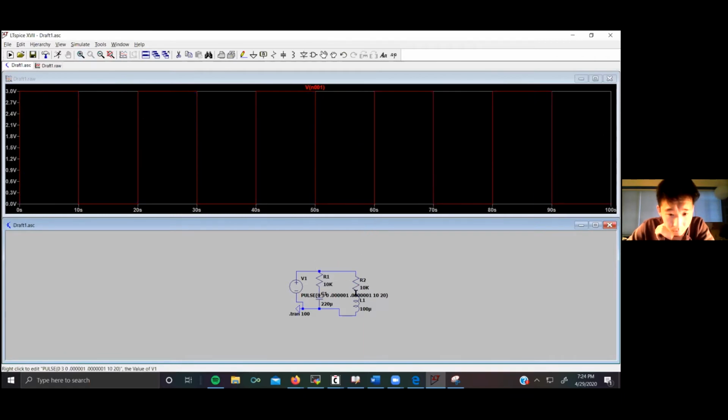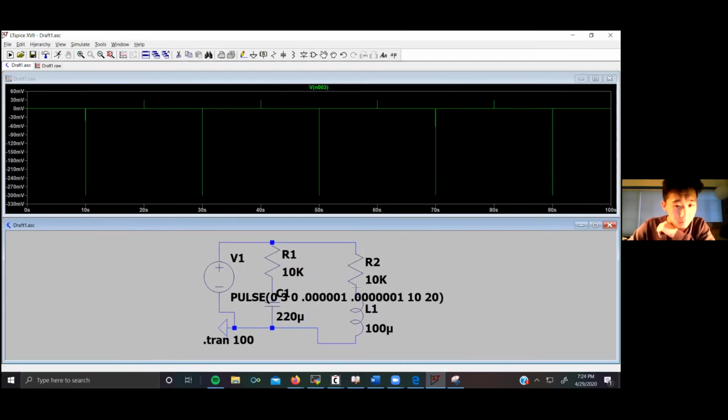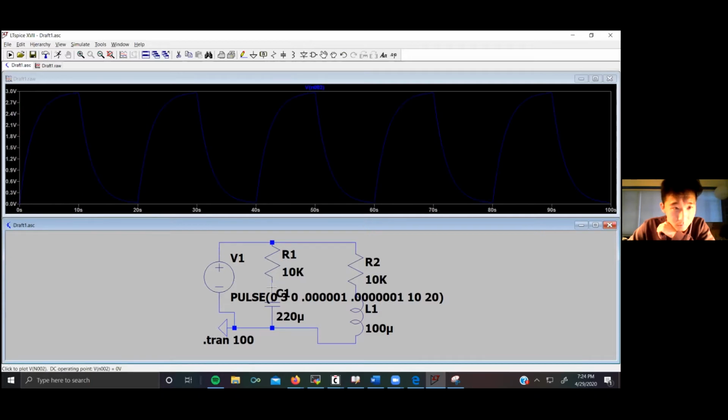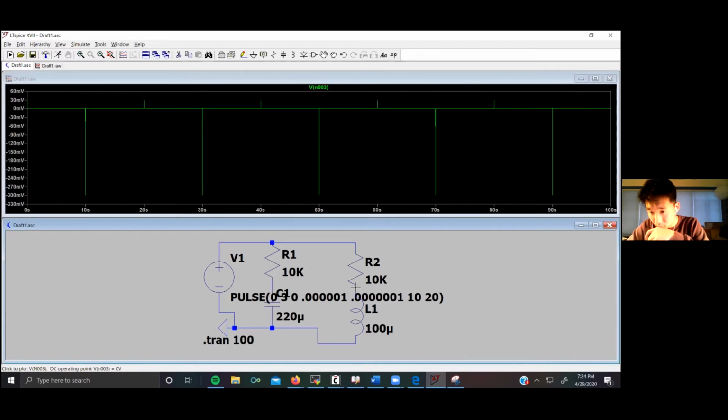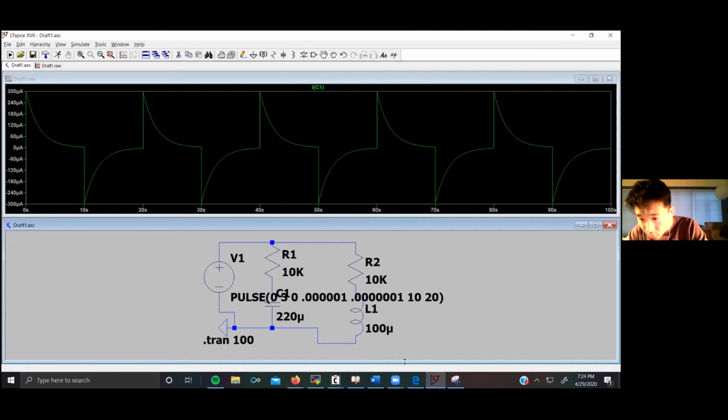So here's our square wave still. We zoom in, take the voltage across the inductor, voltage across the capacitor. We can see the properties that we would expect to see when we have a sudden change in voltage for, say, the inductor. We just get these normal impulses, right? But if we look at the current, we see the square wave again, versus having these weird spiky shapes. Okay, here we'll go to another.